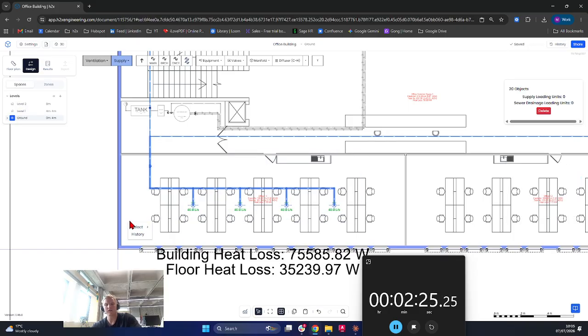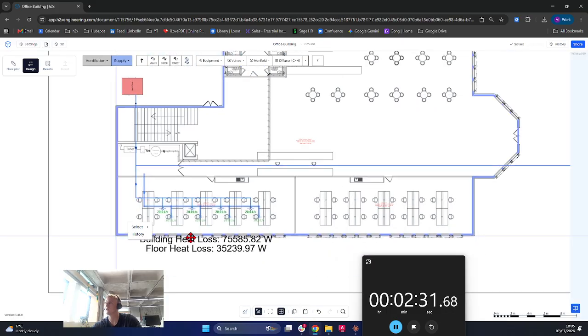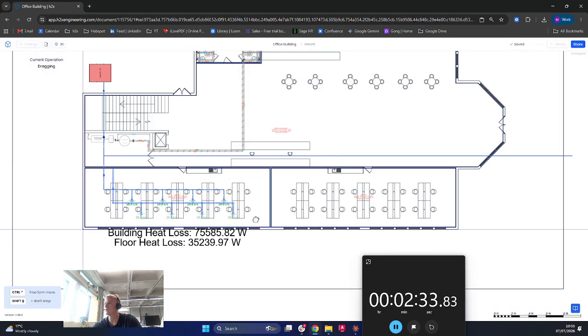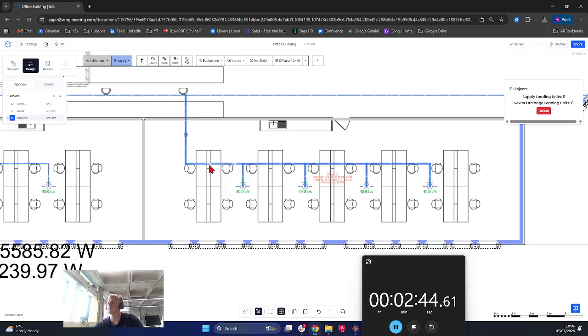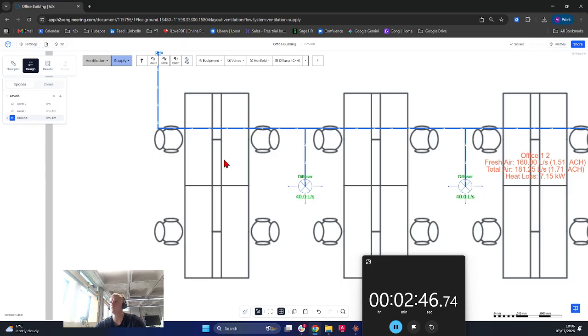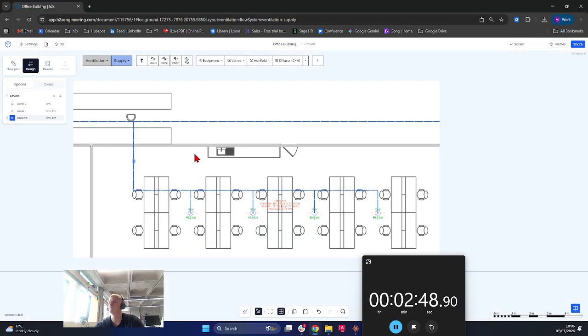Now, if I do a right click and drag, I can select that entire setup and hit the copy and paste buttons at the bottom of the screen here and drag that over and across to the other office location. Now we'll know that it's connected up because we'll get a little flash there on the connecting duct. And if I let go, you can see that those ducts go from being transparent to fully opaque with little arrows indicating the flow direction.